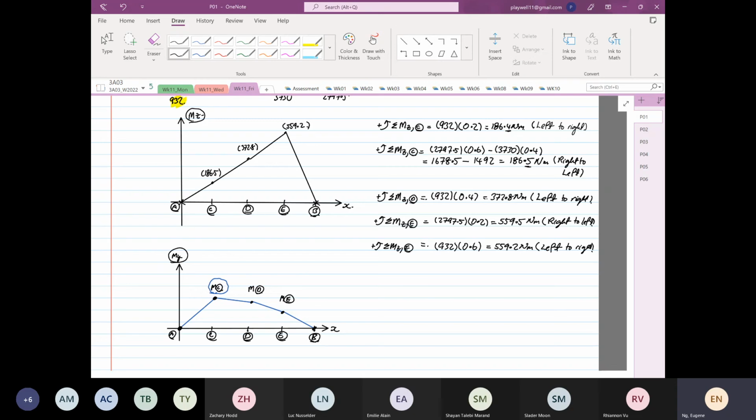Yes? Okay. So what we are trying to achieve down here is to satisfy or find the equation J over C is equal to the square root of Tx squared plus My squared plus Mz squared, and then divide by shear stress allowable. Okay.